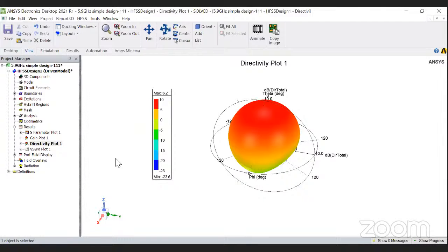Here our gain value is 4.7 divided by 6.2 into 100%, which gives exactly 72 point something percent. But in a microstrip patch antenna, 58 to 60% and above is acceptable. So it has 72% efficiency, and this antenna is perfectly matched for V2X application.